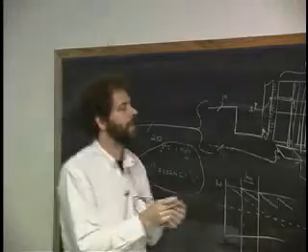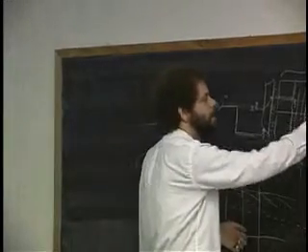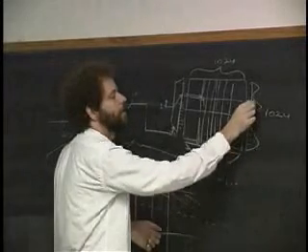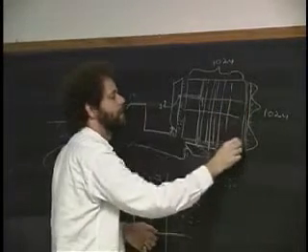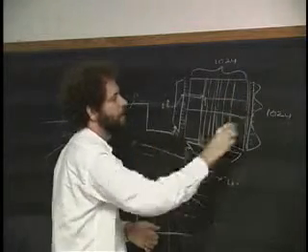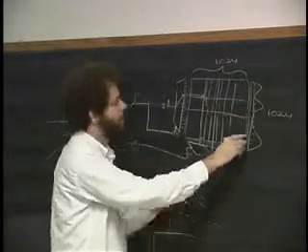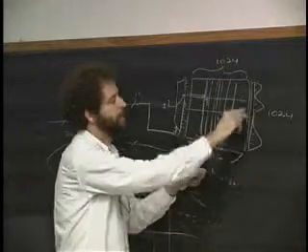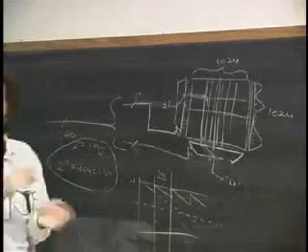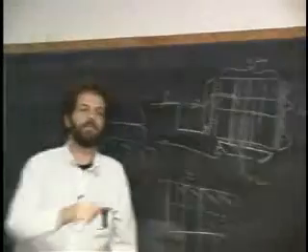One of the things that they do now is that they have what's called a dummy column, like this, that they always fill up, okay? And another one that they always set to 0. When they choose any column, they suck down from here too, and they look at where the one you're checking falls with respect to the references on the end, which are always full or always empty. And so that's another way to calibrate it.